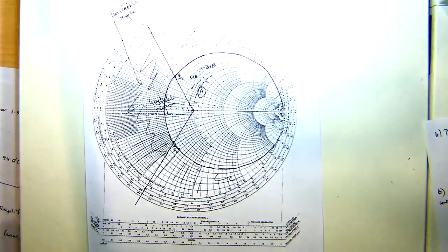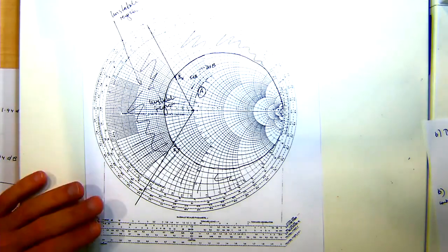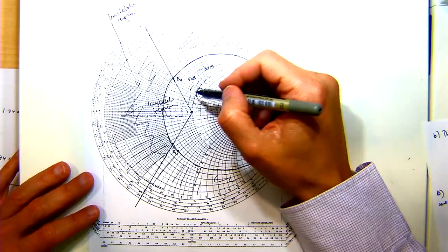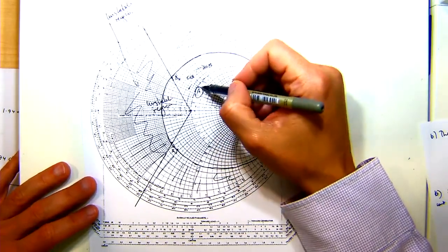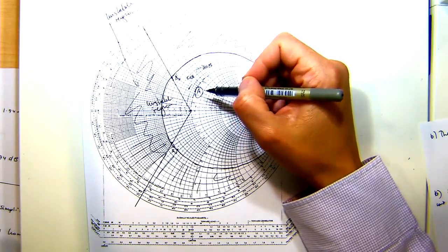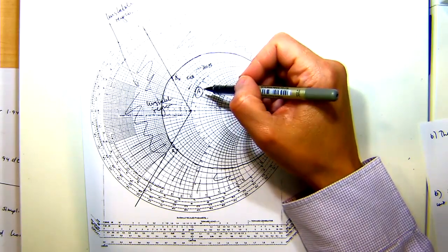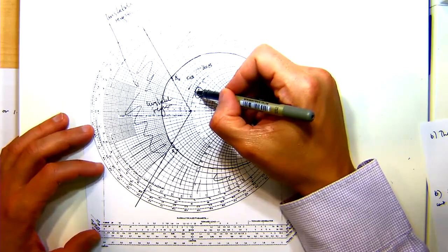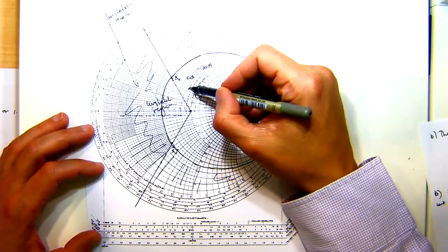So I'm saying if I'm on my 3dB gain circle, what should my impedance be so that I have the most stable network? And that's all I'm saying: on the 3dB gain circle, if you wanted to achieve 3dB gain from your source impedance matching network, the best that you can do, the most stable point, is this point here. If you were at 5dB, it would be here.